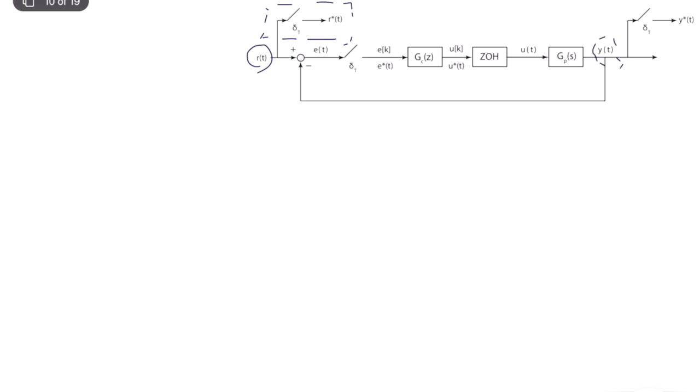It's the output, and we are also sampling y of t for analysis using the idea of pulse transfer function. However, there's a difference block here. E of t is equal to R of t minus y of t. When we sample E of t to obtain E star of t, we also sample R star of t minus Y star of t. So it's not that we are just virtually sampling Y and R. We technically sample their difference, since it's a linear system, at this sampling phase.